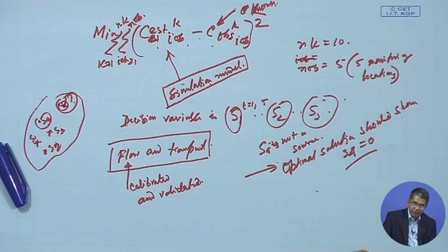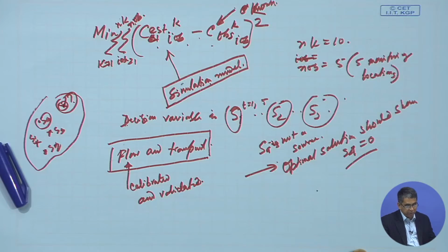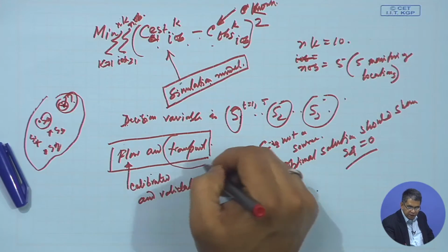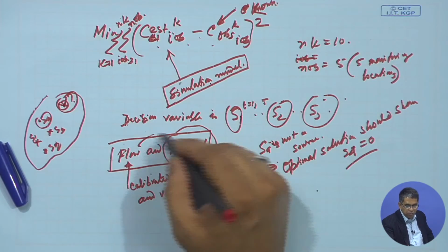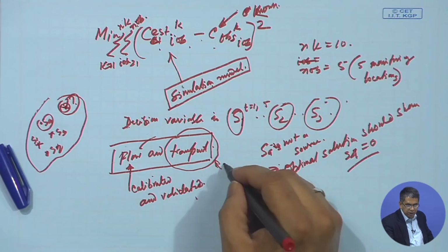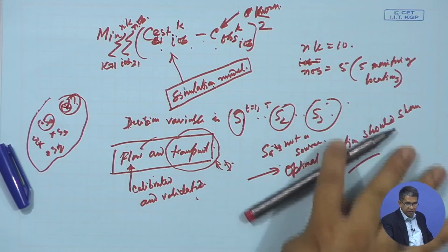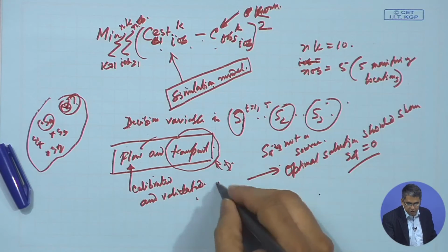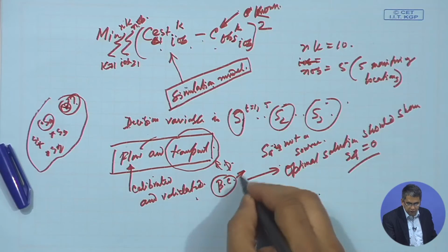Because if you could calibrate that model, then you do not have to go for source identification, you know the sources. Okay. So, first I have a calibrated flow model, and also I implement the transport model, of course. It will use the flow model output, and maybe it will need the dispersion coefficient, all these things. It must be the best estimate you have, and also the boundary conditions are necessary, that you have to give for the transport model. Without that, it might not be acceptable.